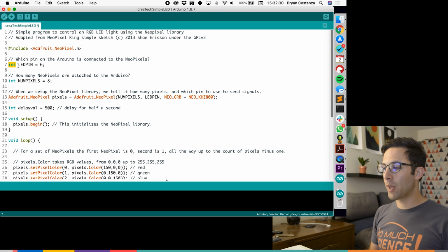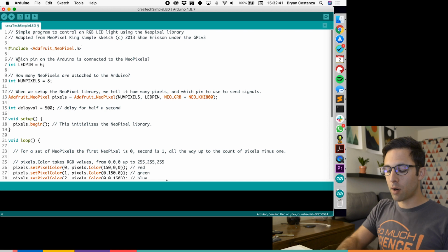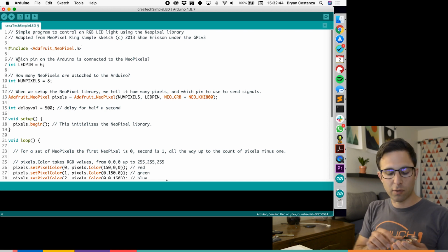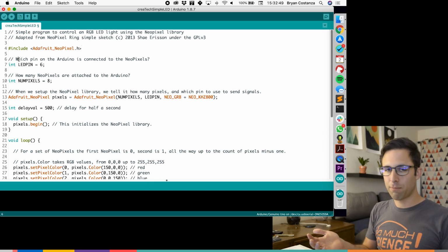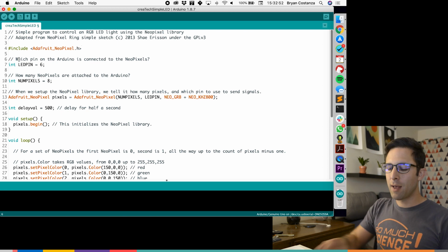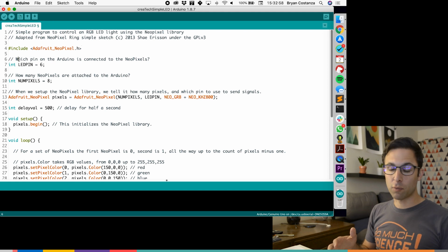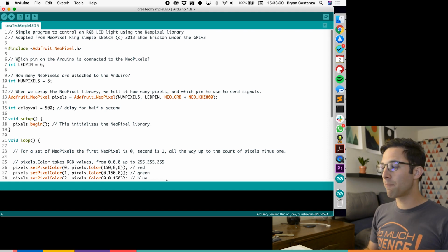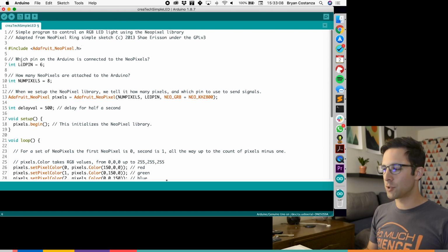So in this case, we have int, that's an integer. And we really want to use integers when we're doing anything where it's counted or when there's discrete steps. So for example, on our Arduino board, we have pins, and there's pin 0, 1, 2, 3, 4, 5 through 13, and some others. There is no pin 3.5 or 7.4. They're only integer values that are valid for addressing those pins. So we like to use integers there, or if we're counting something. Sometimes it makes sense to count in our program. If it's just going 0, 1, 2, 3, 4 like that, we'll use integers there.